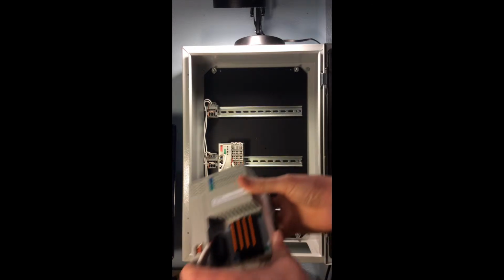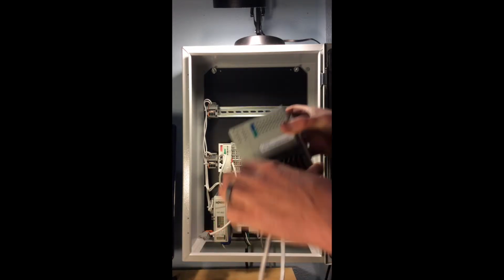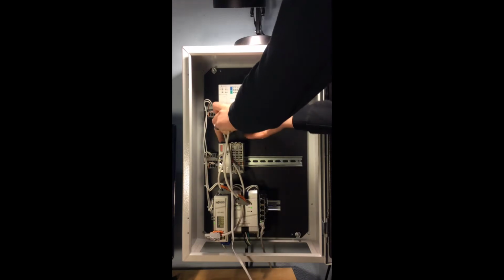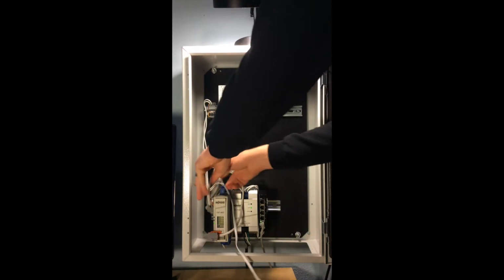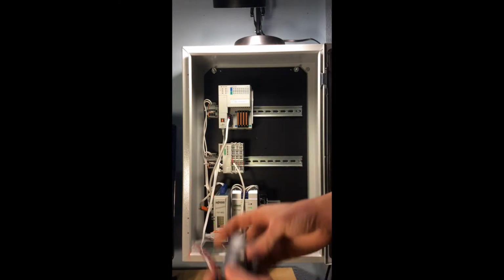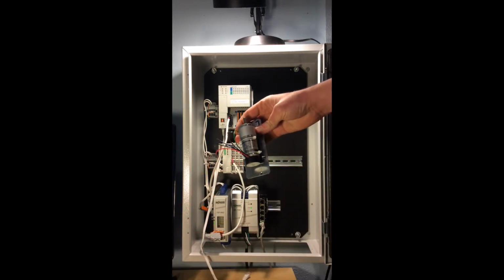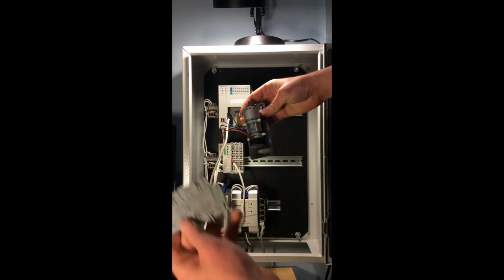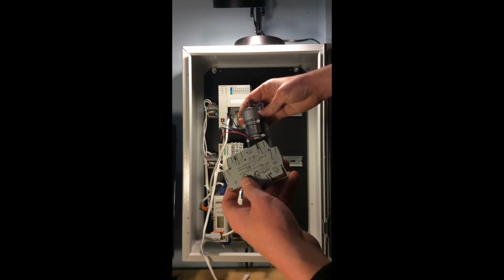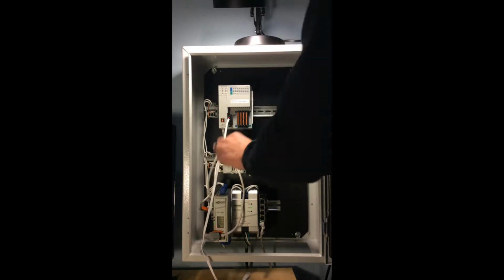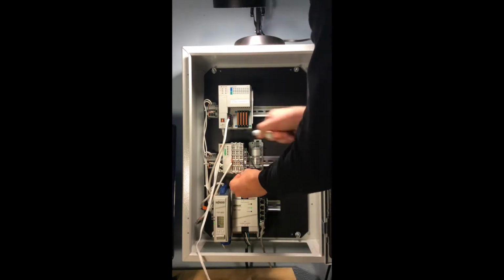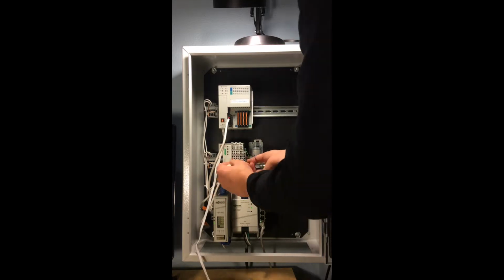For test purposes, we'll be using an Allen Bradley L16ER CompactLogix processor. And for our motor hardware, we're going to be using a small 24 volts DC motor with integrated encoder. The encoder on this motor is 5 volts, so we'll use a WAGO 24 volts to 5 volts DC converter as well. Once this is wired up, we're going to then move to the settings on the coupler itself.